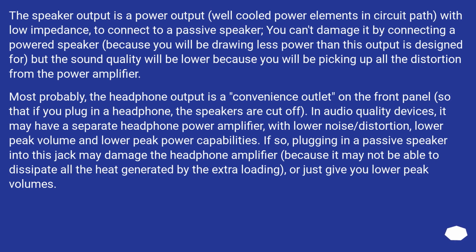Most probably, the headphone output is a convenience outlet on the front panel, so that if you plug in a headphone, the speakers are cut off. In audio quality devices, it may have a separate headphone power amplifier, with lower noise/distortion, lower peak volume and lower peak power capabilities. If so, plugging a passive speaker into this jack may damage the headphone amplifier, because it may not be able to dissipate all the heat generated by the extra loading, or just give you lower peak volumes.